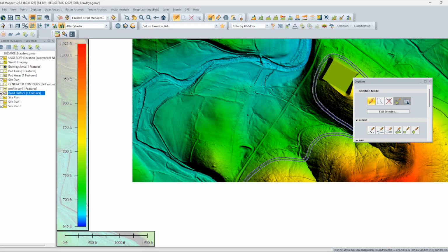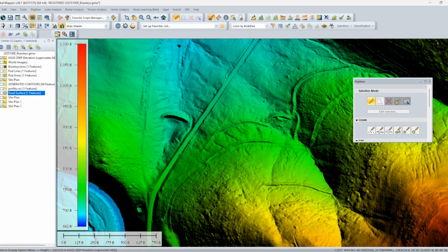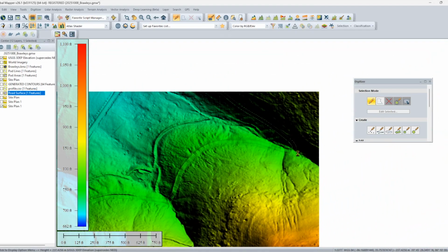What's happening here is that the ground isn't being reshaped to match any grade value. It just follows the natural terrain and flattens the road right on top. And of course, that's not how any real road behaves in the field. As you can see, the road looks almost non-existent and it's barely visible because the vertical component of the road is not processed.